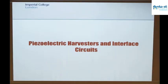Okay, right, so specifically then talking about piezo interface circuits. We're going to try and leverage a little bit of what we've just done in terms of the basics of power electronics. That means we're going to try and operate things in switch mode. We recognize, therefore, that whenever we transfer energy from one storage element to another, from the capacitance on the piezo through to the energy storage element in the system, we're going to have to do that through an inductor, otherwise we're going to have energy loss.